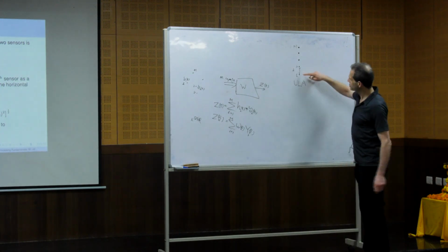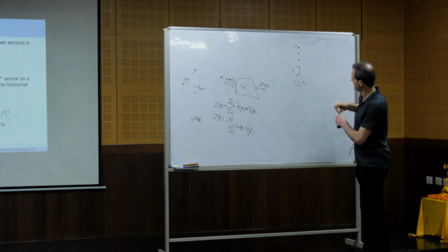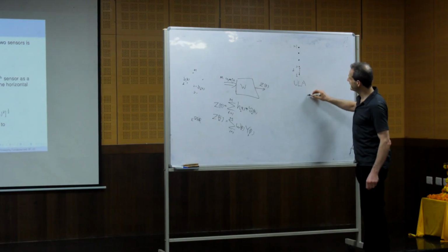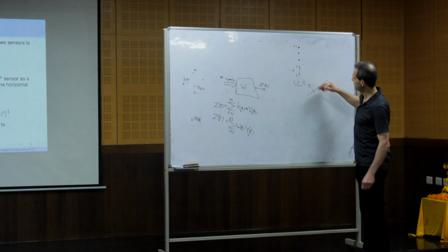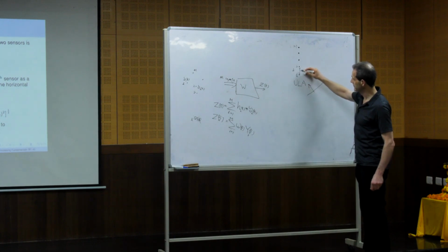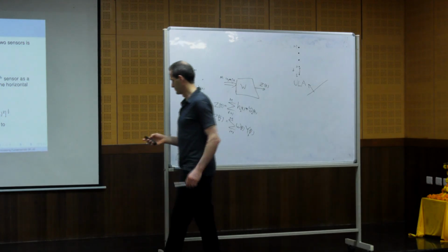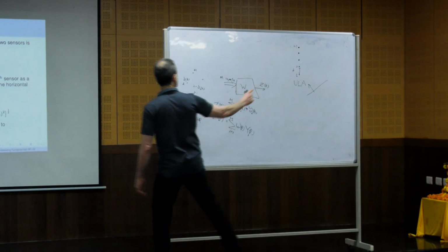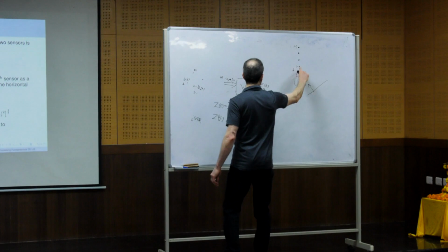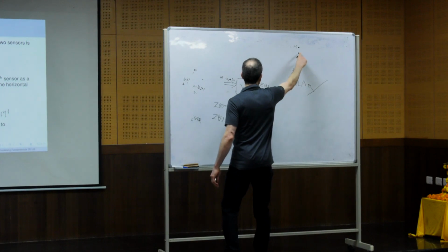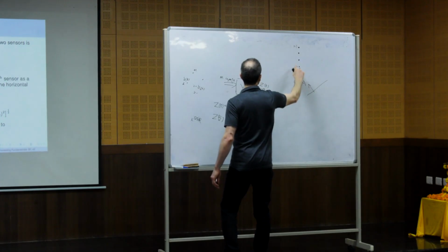So when we measure the distance or the delay of the propagating wave that comes from a certain direction, we could assume that the distance of the n-th sensor to the first sensor is d multiplied with n.